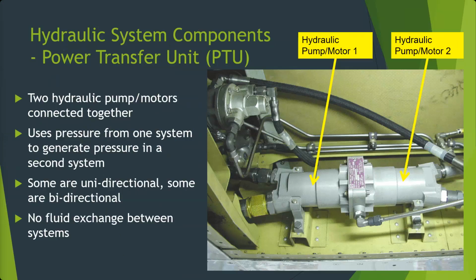So in this case here, you've got say like a pump driving a motor over here. This is not a case drain. This is actually if the seals leak on either of these, it drains this cavity inside of here. It's the same thing that happens on that pump. Like I was saying, if the seals leak, if it's hydraulic fluid, it's the pump. If it's engine oil, it's the engine seal. Okay. But you can see there really isn't a case drain. Again, these are not running constantly. They are an auxiliary or backup system most of the time.